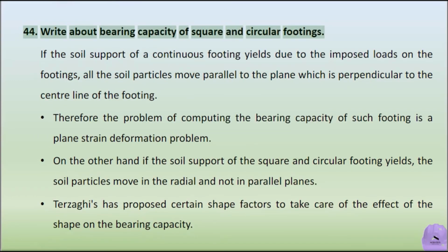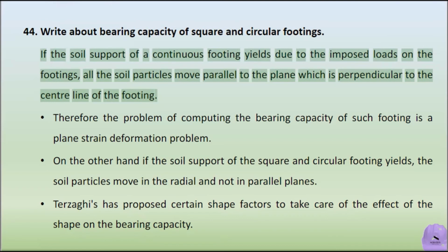Write about bearing capacity of square and circular footings. If the soil support of a continuous footing yields due to the imposed loads on the footing, all the soil particles move parallel to the plane which is perpendicular to the center line of the footing.